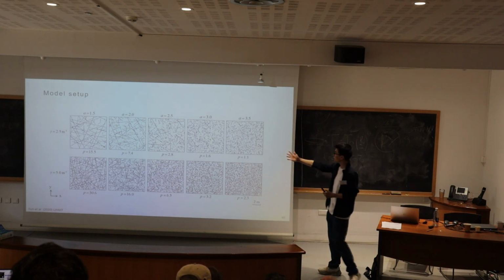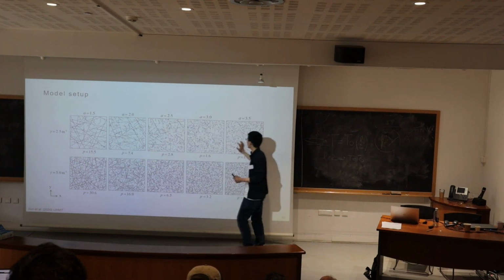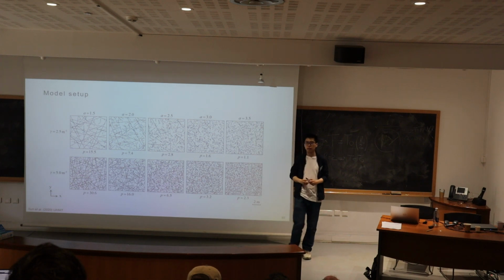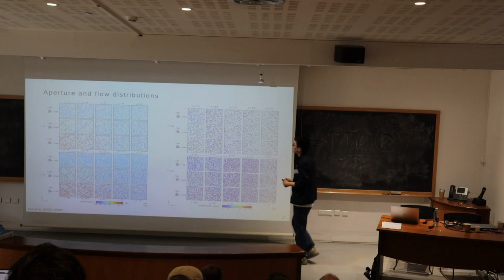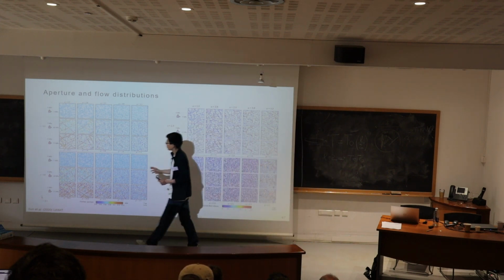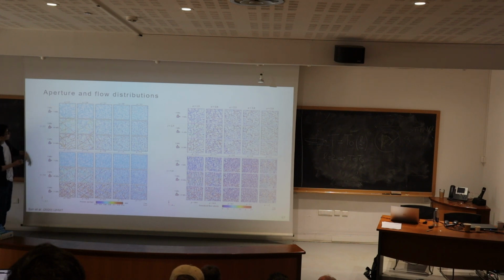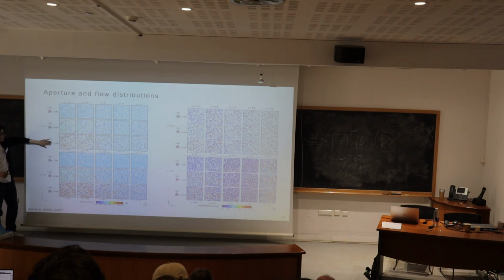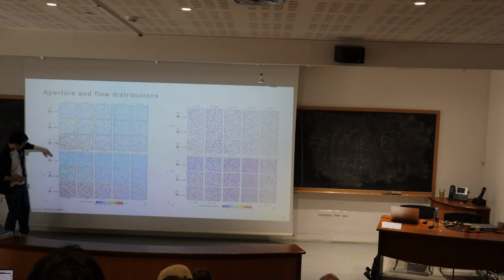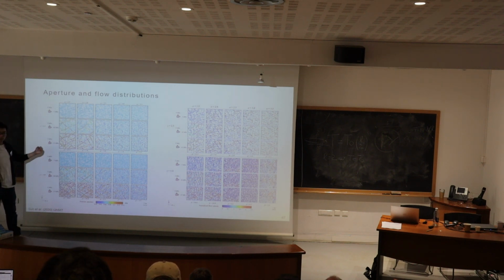Okay, so towards the left side, the system is more connected. Towards the right, it's more dominated by the small cracks. Here are the results of the aperture distribution, where we can see that when we increase the stress ratio, so basically increase the differential stress, from 1 to 2 to 3, some large apertures are generated along the long fractures.